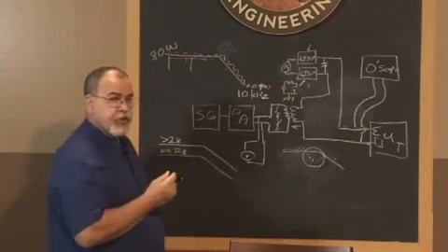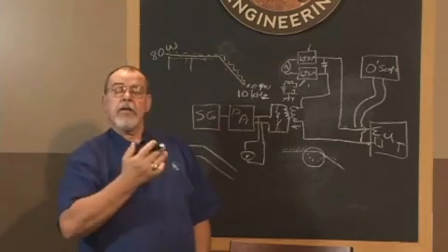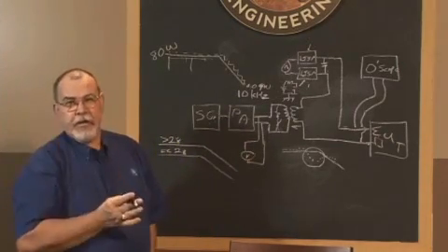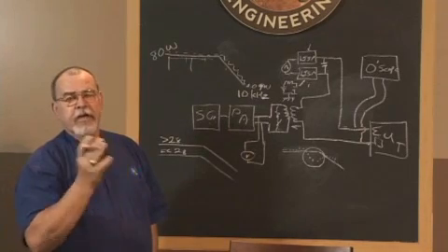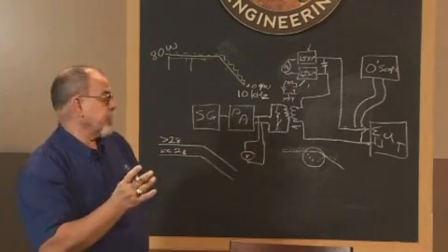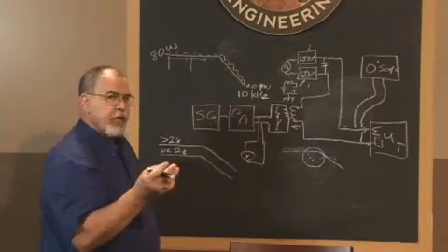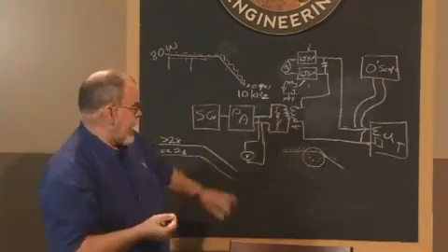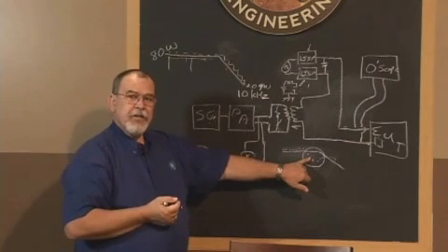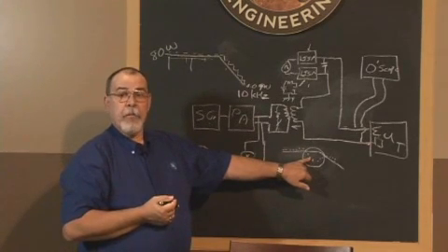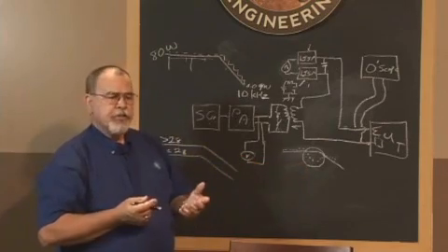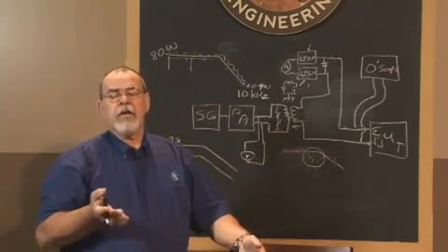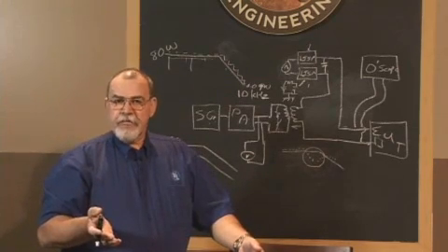Let us say that the test article did not behave, that something erroneous happened. Well, we'll say the fan quit running. You know, at some point the ventilation fan stopped operating because of whatever reason. We now need to know what was the threshold of that susceptibility. At what voltage did that circuit stop operating correctly? Now, what stopped operating? Well, if it ceased to run might be a threshold point. Clearly that would indicate a severe problem.